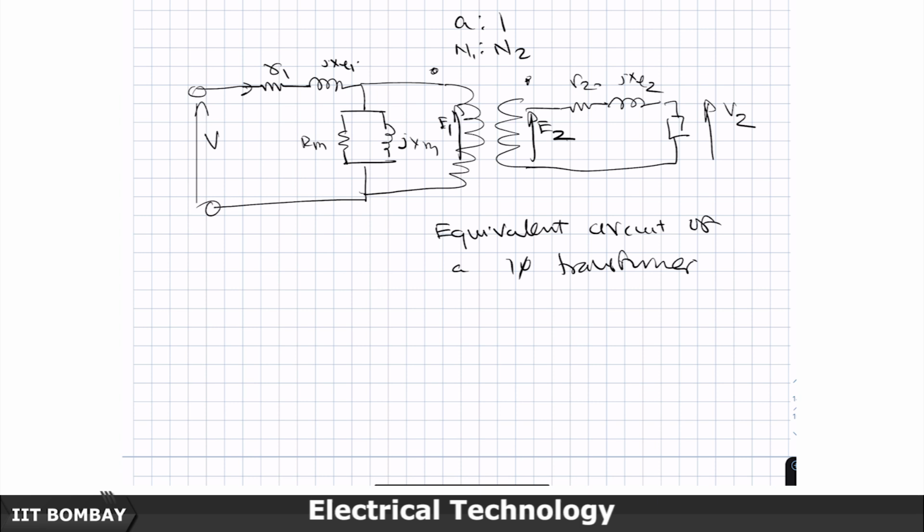In this, the harmonic effects of the no load current have been ignored and adjusted, but the RMS value of the currents has not been ignored, because we will do the open circuit and short circuit tests and measure the parameters later. There you will directly measure the net losses, and V by I will give you the no load current, and then that is what you are going to split into these two components.